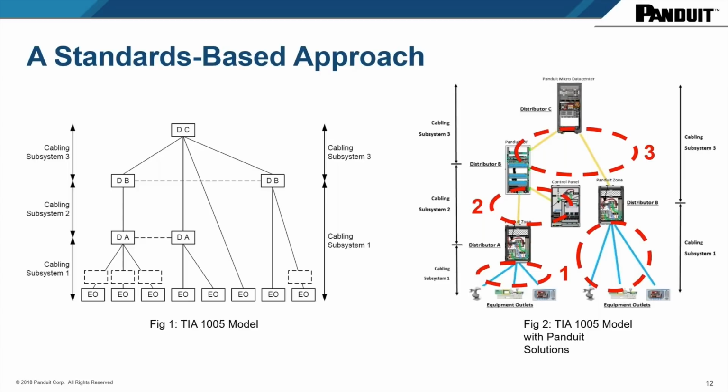Generally, the connection between an edge device and a zone enclosure is under 100 meters. Therefore, you could use copper. The specifications 568 and 1005 state that when you run copper cabling, you shall not exceed a length of 100 meters. Running fiber, you could go at higher distances. So shorter distances are generally copper, and this is an extreme condition.